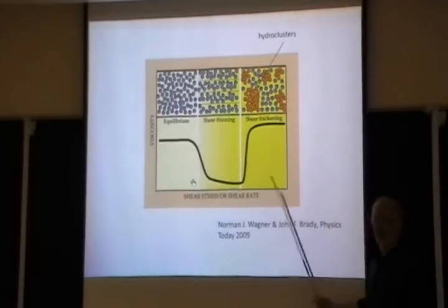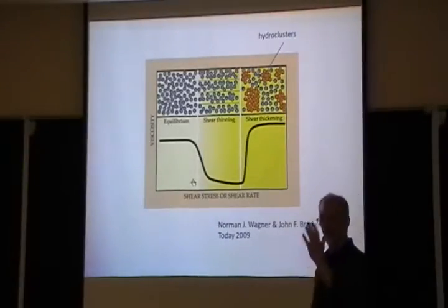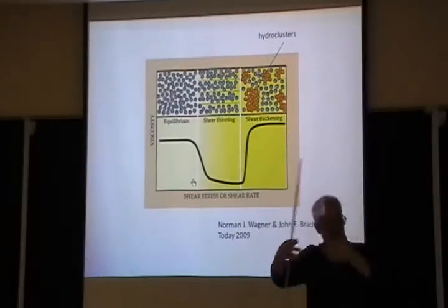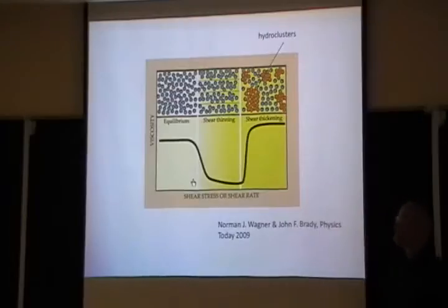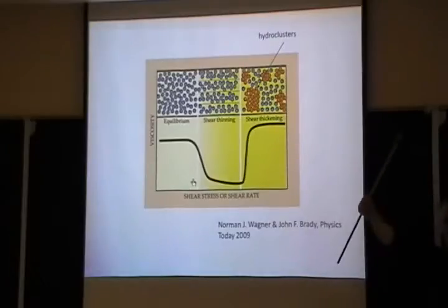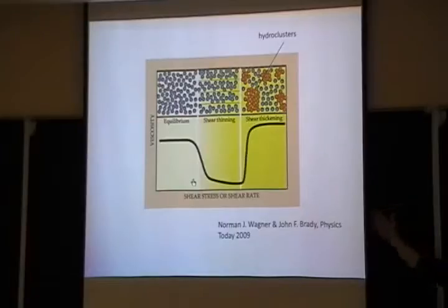And it works okay, except that you would guess then that the threshold for this would be a critical Peclet number, where you have to push harder together, otherwise the stuff would flow apart. And it just turns out that the Peclet number argument doesn't always work. In fact, there's a big argument as to whether that actually can work. The idea, furthermore, is that if these things grow and eventually span the system, that is the upper and lower plate, it would percolate across and you could support stresses all the way across, and there would be strong shear thickening. Except nobody has shown that this actually works.